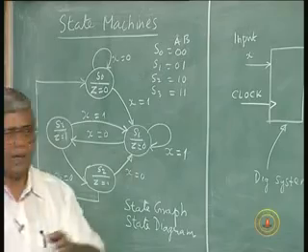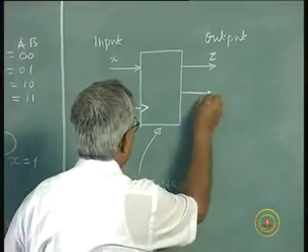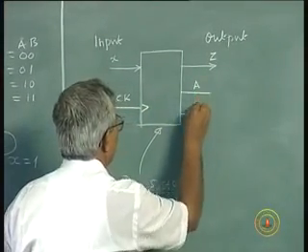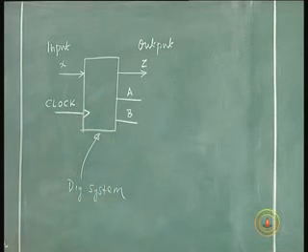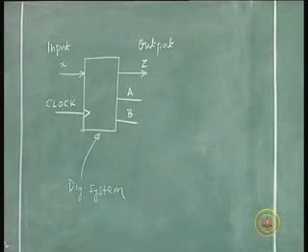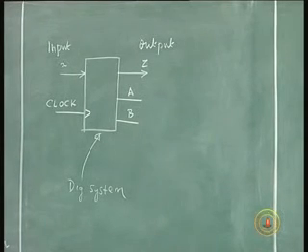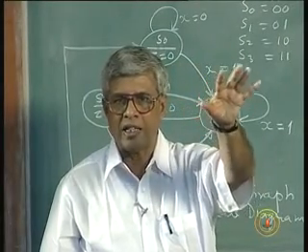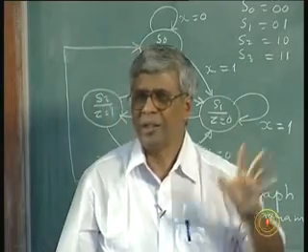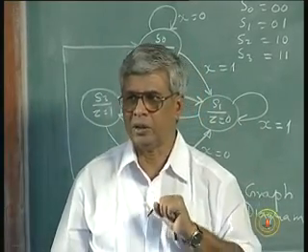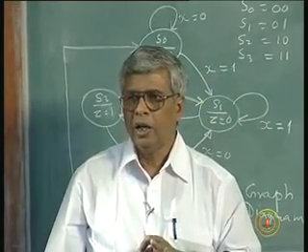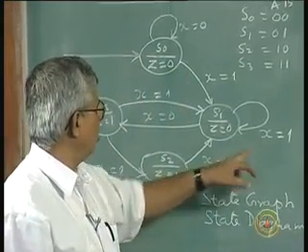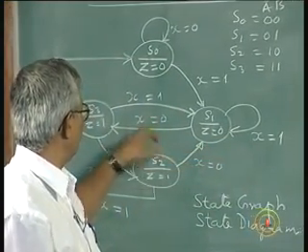So that means I need to have these variables A and B coming out of this. Since this value of A and B is required for me, at least for 1 clock period, only then I can determine what state it will be in next. Let us assume the circuit has just now reached S1, which is 0, 1, and input of x is equal to 0 has occurred.